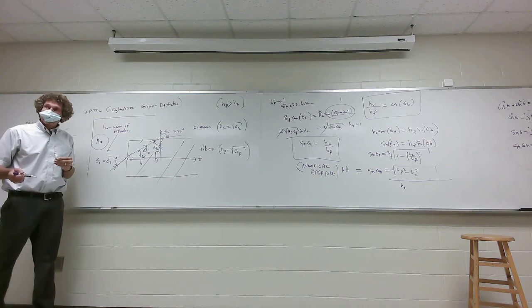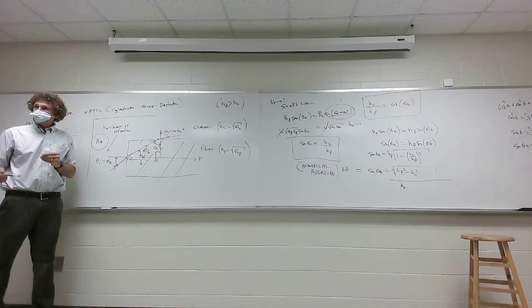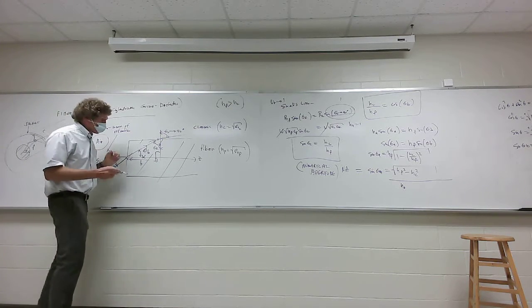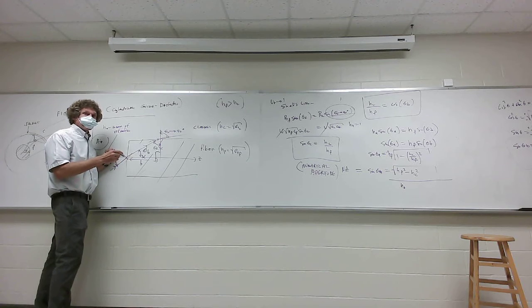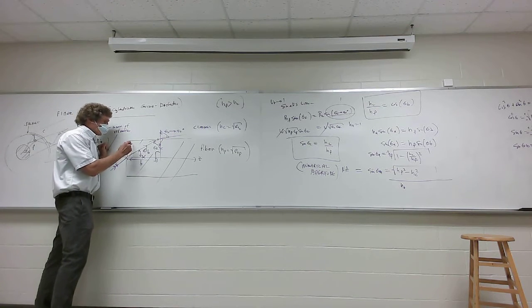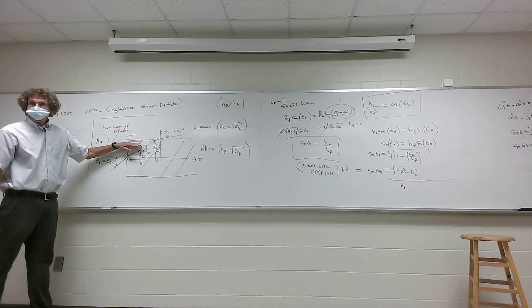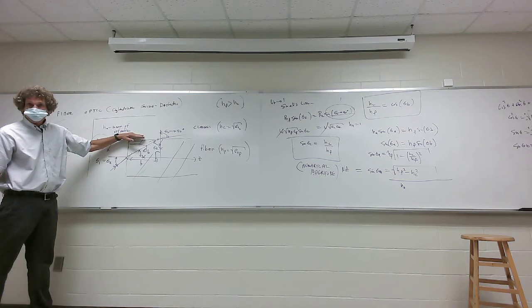Now here's the other thing I've got to tell you. When you have fiber optic stuff, there's something called graded index that he mentions in the book. It's called GRIN, graded index materials. What will happen is they will have a transition from the fiber index of refraction to the cladding, and it will change, not instantly, but gradually from one to the other, right? That happens. There's a lot of problems with that, but there's a reason for it.